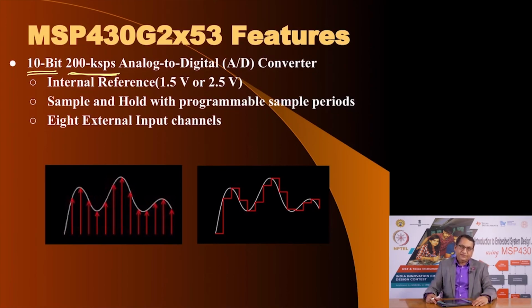ADC also requires a reference voltage, and you could choose an internal voltage reference of 1.5 or 2.5 volts. Of course, if you are going to utilize an internal 2.5 volts of reference voltage, then your supply voltage has to be obviously higher than 2.5 volts. You could also have an external reference voltage, and we will see the pin out of a sample microcontroller. You will see that there are certain pins on which you can connect external reference voltages.